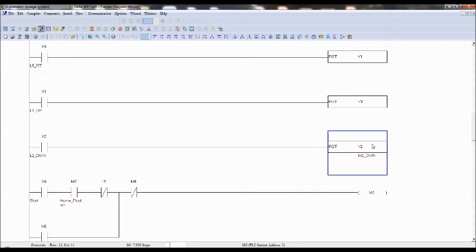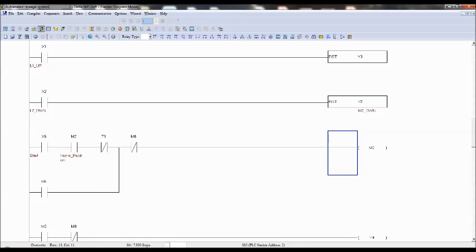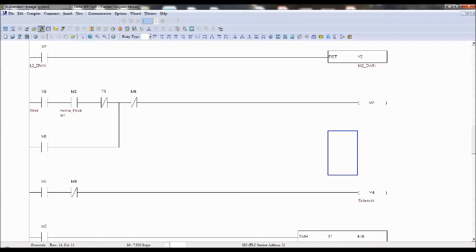M3 is on, so what is our requirement? If M3 is on, the storage system should start. Whatever the home position is, I will consider it the first position. In the storage system we have taken 4 positions: the leftmost down position, the rightmost down position, and the upward leftmost and upward rightmost positions. So there are 4 slots. Whenever M3 is on, the solenoid should be on, because I am assuming the home position itself is the first slot.